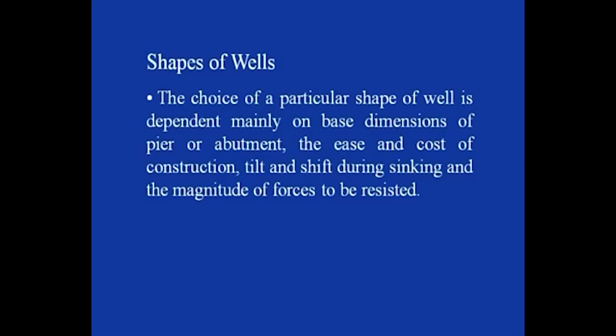Now let us see what the advantages and disadvantages of these different shapes of well are, in what conditions these are preferred, and in what conditions these are not employed. The choice of the particular shape of well depends mainly on the base dimension of the pier or abutment.